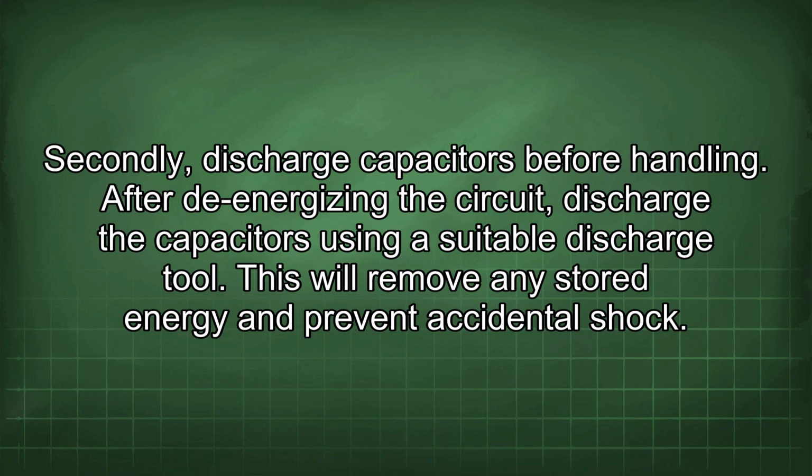Secondly, discharge capacitors before handling. After de-energizing the circuit, discharge the capacitors using a suitable discharge tool. This will remove any stored energy and prevent accidental shock.